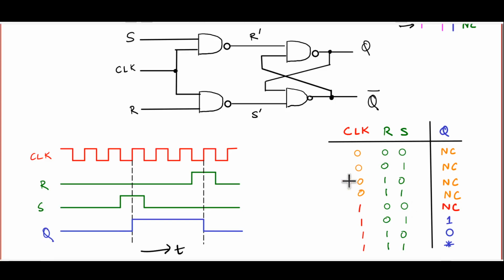The same kind of behavior can be seen in this graphical representation here in what is called a timing diagram. Now, in most textbooks, you don't have this horizontal axis labeled, but it's really the time axis. It clearly shows how the signals change as time is flowing. The clock here is a square wave which goes high and low at regular intervals.